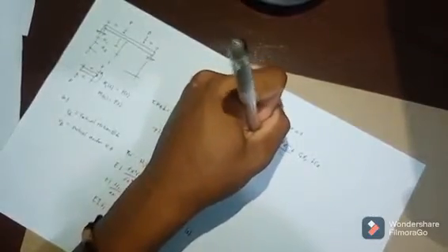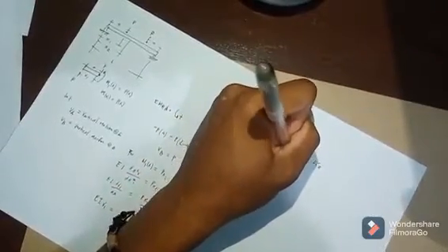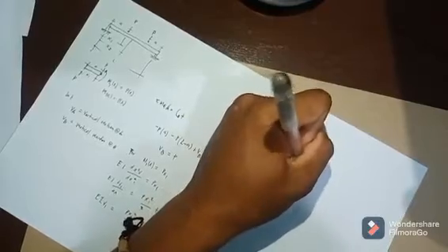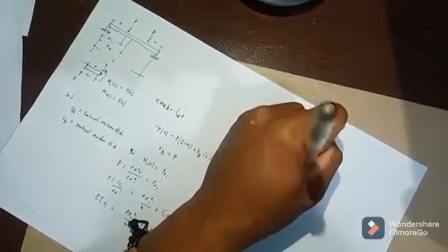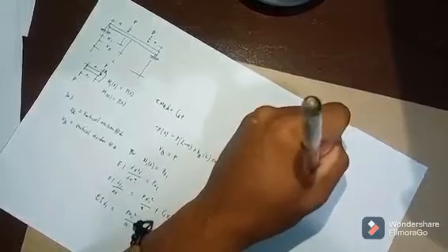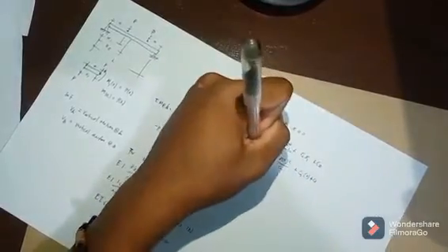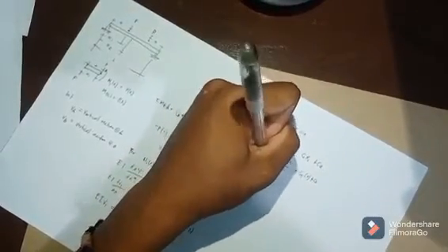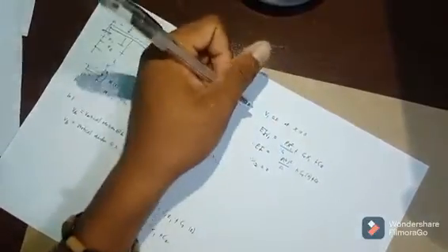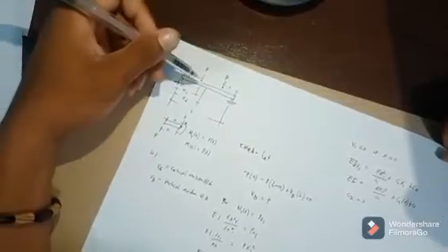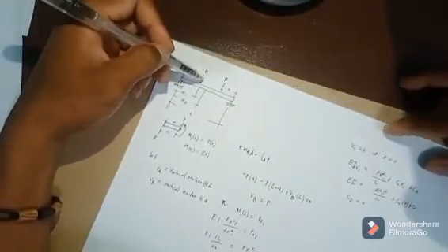If v is equal to 0, then 0 is equal to P times 0 cubed divided by 6 plus C1 times 0 plus C2. So we get C2 is equal to 0. This is the solution if we are focusing on the coordinate x sub 1. Next is the x sub 2 coordinate.